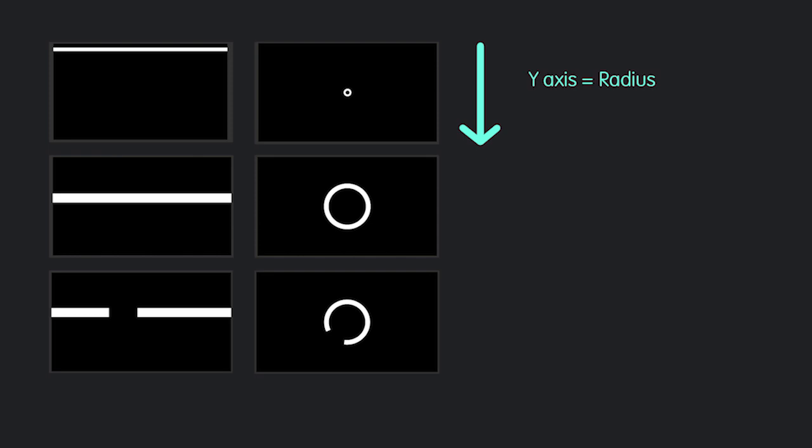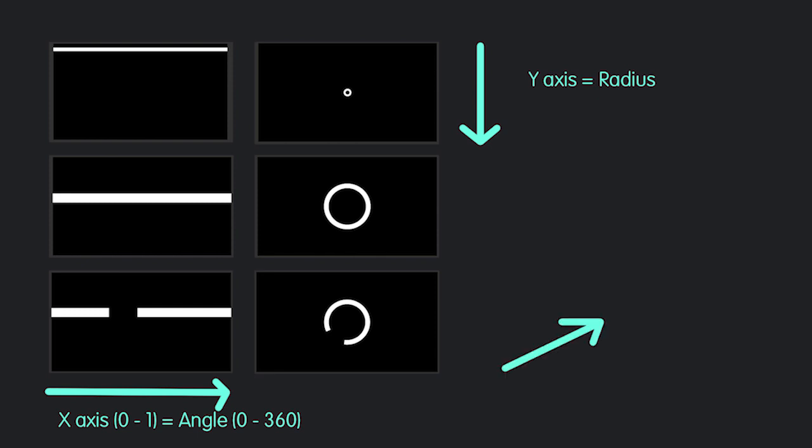Looking at the last two images, it seems like the screen space x-axis represents the angle of rotation, where we can remap the x-axis from the left to the right of the screen to a range between 0 to 360 degrees of the circle. With that logic, we can also apply the same rule to our z-axis in Houdini to get the other angle of rotation, so we can create our spherical coordinates. With theory out of the way, let's try implementing this logic in Houdini.